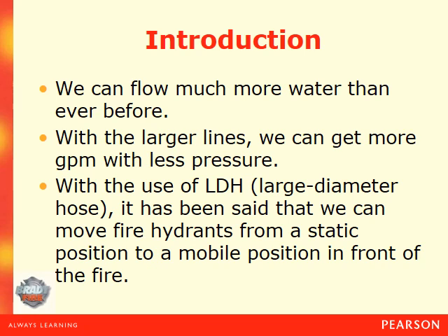As well, with the use of LDH, which is large diameter hose, it has been said that we can move fire hydrants from a static position to a mobile position in front of the fire. Essentially, we are getting the water closer to the fire, thus reducing our friction loss and allowing for greater gallons and pressures to be delivered.